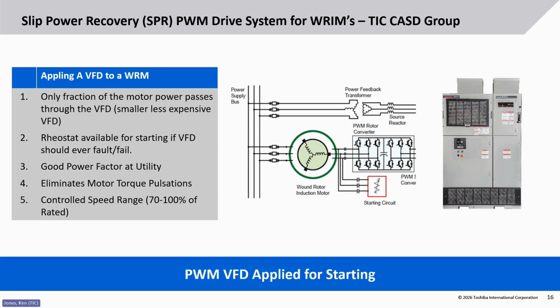So you get the benefits of both the PWM starting circuit as well as the improved characteristics of control at a lower speed. Benefits are high starting torque and then variable speed output. But you do have all of the resistance plus the VFD in the circuit. So there is a higher upfront cost.